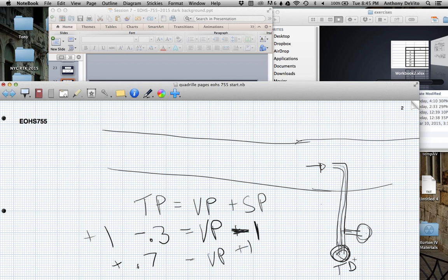And what was coming in the tip? Total pressure, right? And what was coming in here? This is the outer tube. There were little holes on the sides of this tube. Is that measuring the velocity pressure? No, all it's measuring is the other pressure that's in here, which is the static pressure. This end measures the total pressure. This end measures the static pressure.